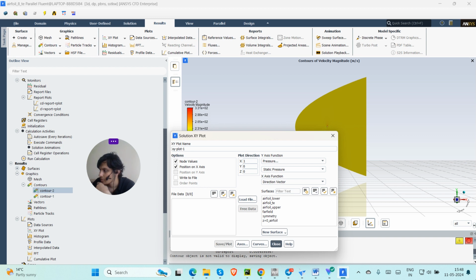It is important to resolve the viscous sublayer of this application, so y plus equal to 1 is desired. Values seen here in the range of 3 to 6 might be a bit high, and for a real problem instead of a workshop exercise, it would probably be advisable to create a new mesh with a smaller first layer height.